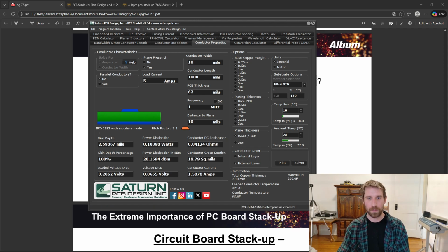And then if we just go to 10 here, we can do over an amp on an external layer. And this is with the 10 degree C rise, which is pretty conservative. We can go higher, we can potentially go a lot higher. So in this, we aren't even at this 130 if you add both of these. So we could even go higher. But point being, I do not buy that you need to have a power plane. That is not mandatory.